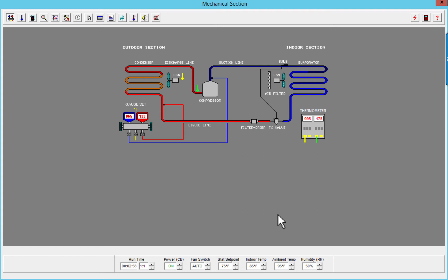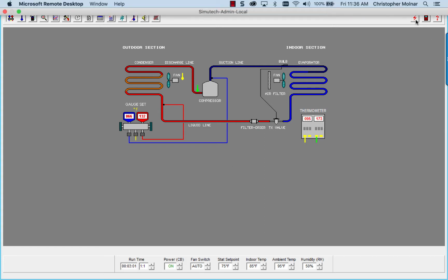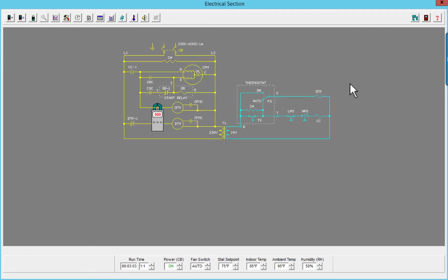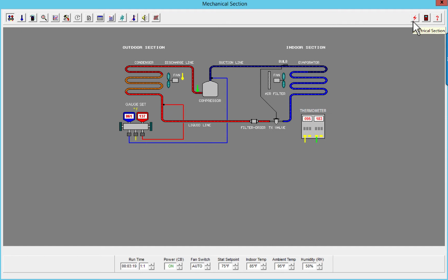You see my pressures are dropping. Okay, if we go back to the electrical side, let's put the amperage back on the compressor motor. Oh, we're still drawing 19 amps there. So we're still drawing a lot of amperage on this compressor. Notice what's happening on my pressures here as well. Sooner or later, the high pressure switch will open. We'll allow that pressure to drop a little bit, and this will come back on. Now, in this case, we have a fan not working whatsoever.